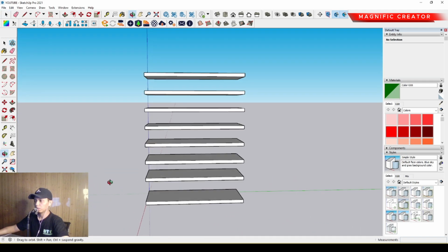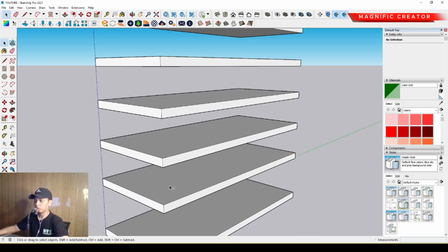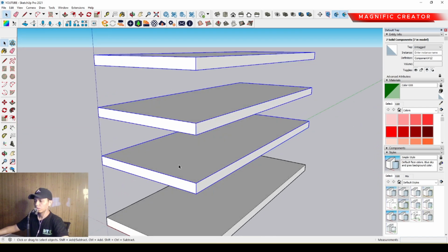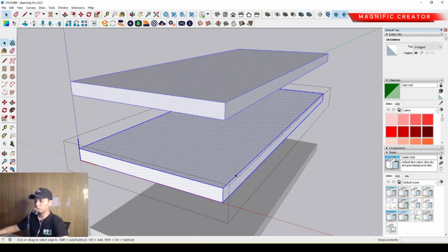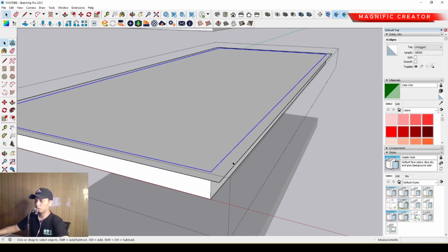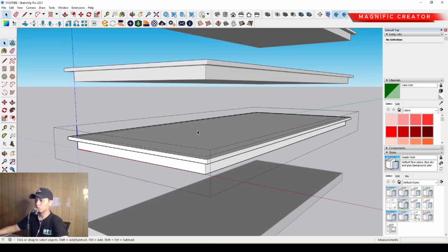In the 7th floor maybe we can decorate the floor. After that we can make it all unique. So we have to make an overslab, and extend the slab extension like this. We can offset it outside around 400 millimeter, so that we can push it down around 200 millimeter. So this is the overslab anyway.